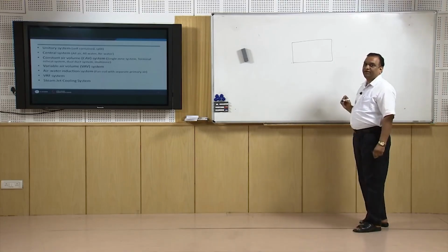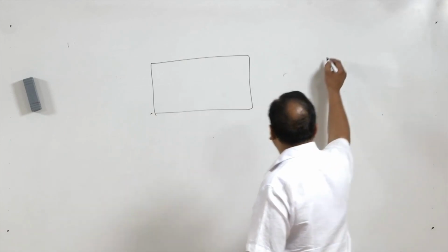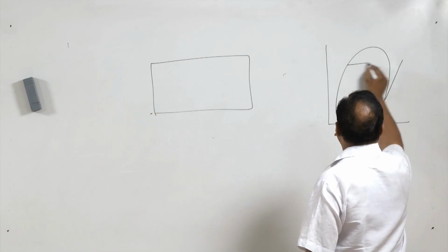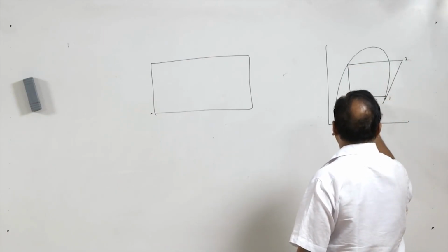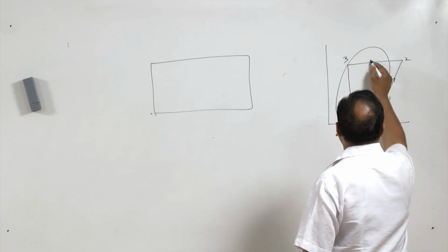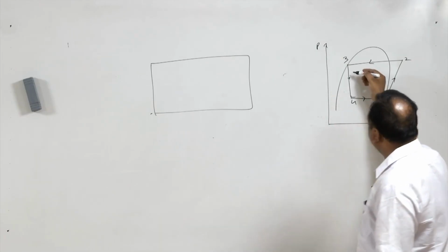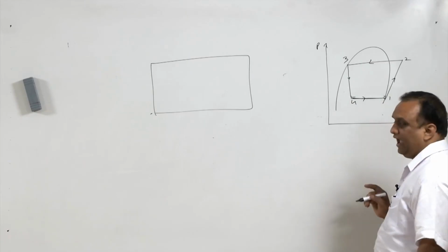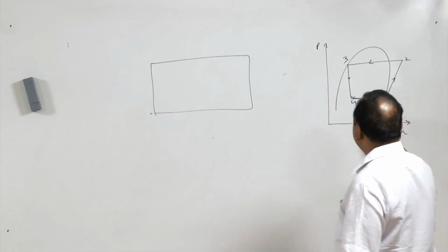It is a direct expansion type of system. Direct expansion means after the expansion valve, points 1, 2, 3 and 4. So in this unit, after expansion in the valve, the refrigerant goes to the evaporator and the air comes directly in contact with the evaporator. This is known as a direct expansion type of unit.